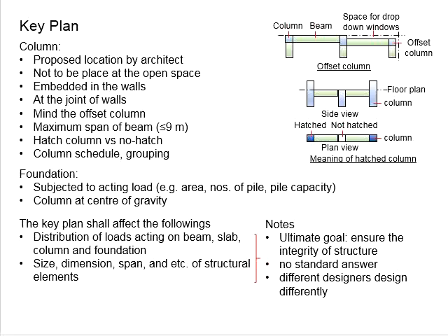This is at least to kickstart the analysis and design. If the proposed size fails, you will need to enlarge the column, and if the proposed size passes, probably you want to do one more trial for a smaller size column to check if you have oversized the columns.